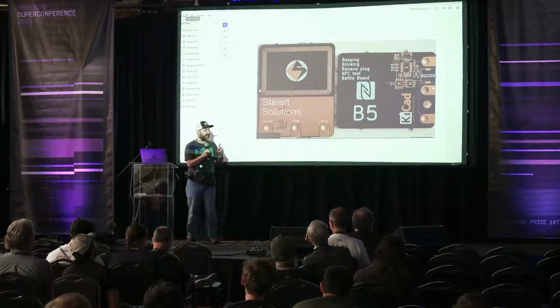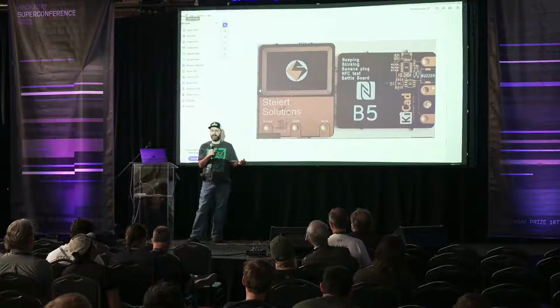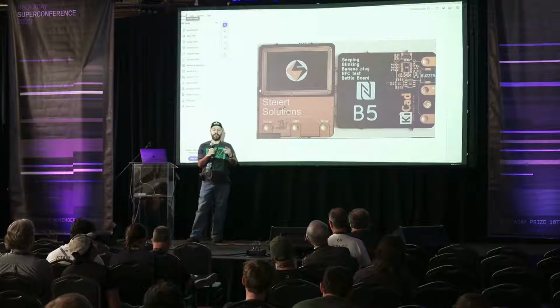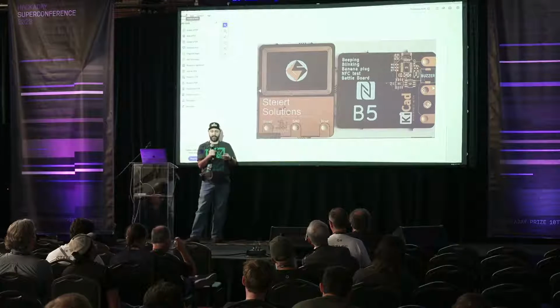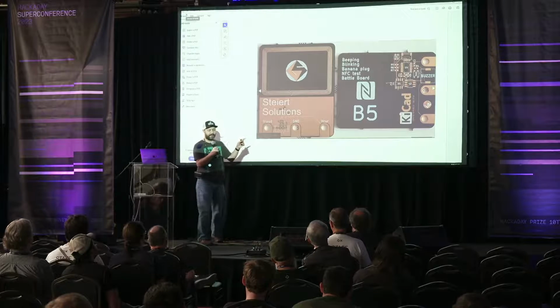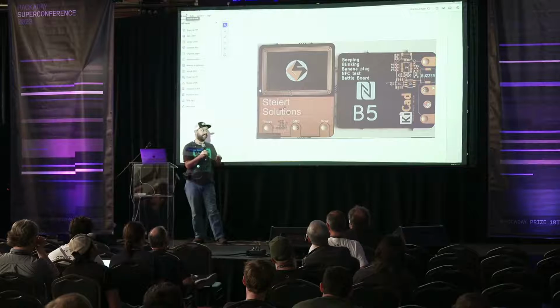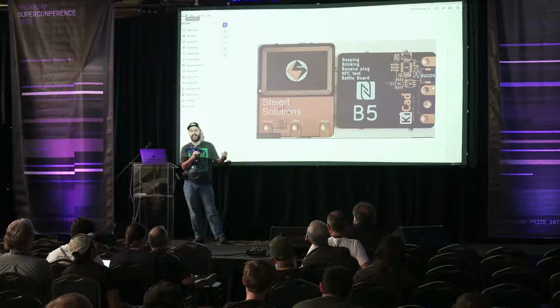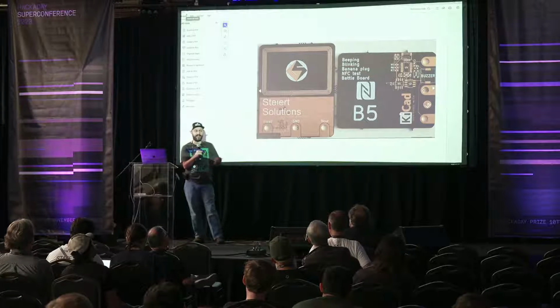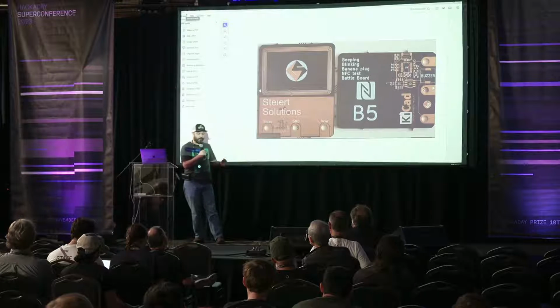One thing of caution, with these antennas, the best thing to do is just reuse an antenna that the vendor provides. Just make sure that the antenna is designed for the same load capacitance as the chip you're using. And NXP has a new NTAG 5 out there, but they changed the load capacitance, so I couldn't use it with the same antenna. So I'm using their older NTAG I2C Plus or something. But yeah, so I've got that.